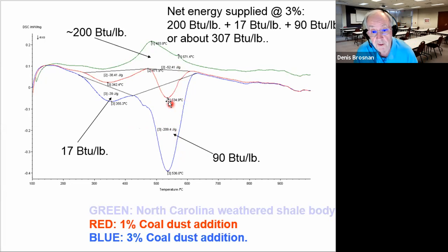If coal was within a product of significant thickness, as in the case of the French brick plant, mining tailings from coal mining, then this heat release took place over a period of time, and they starved the kiln for oxygen in the preheat section so that they could maintain this oxidation toward the burning zone of the kiln, and used no fuel whatsoever once they had reached steady state operation. Now I'm going to talk about combustion of solid fuels next time.